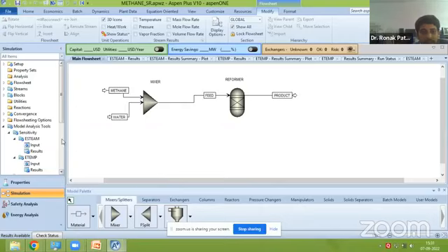So we require, for example, if an ethanol water system is there, which forms the azeotrope, that azeotrope can be broken with the help of deep eutectic solvents, and several papers are also published on this particular area. So they are using DES, deep eutectic solvents. As I told, they add how the density is going to vary, how the viscosity varies. They add the molecular structure of the DES, right?